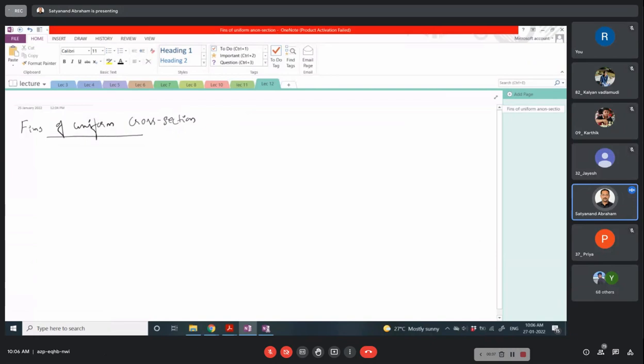So if you remember the equation, the basic equation is d by dx of Ac dT by dx minus h by k dAs by dx into (T minus T infinity) is equal to 0.